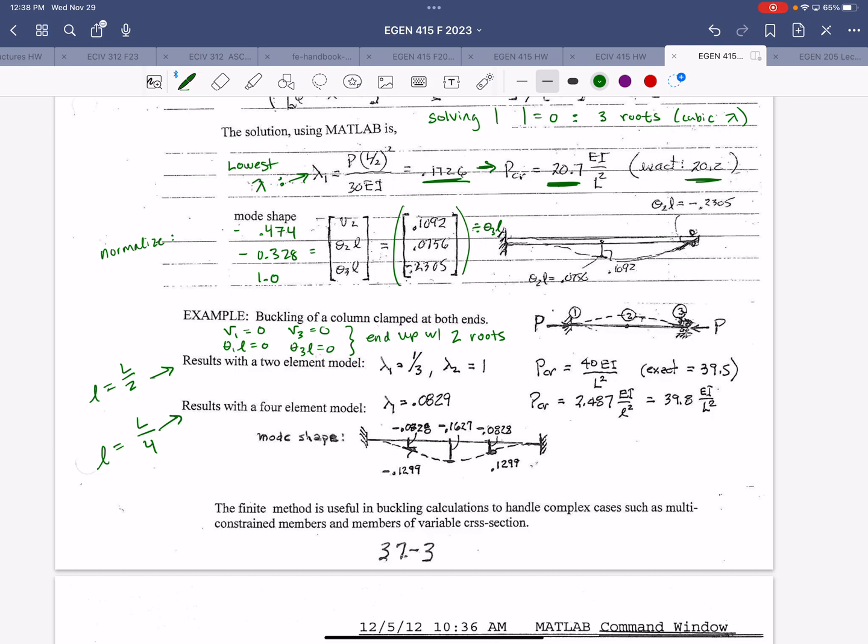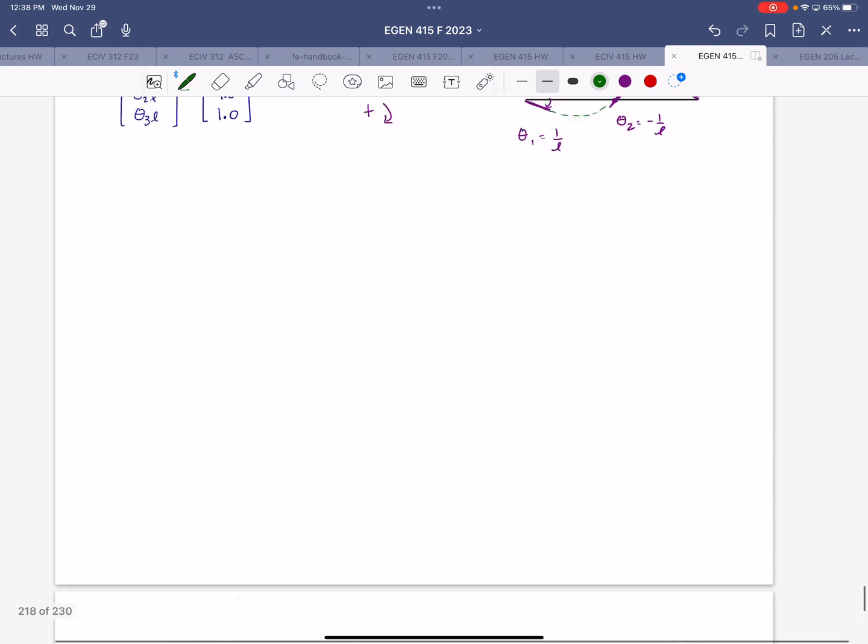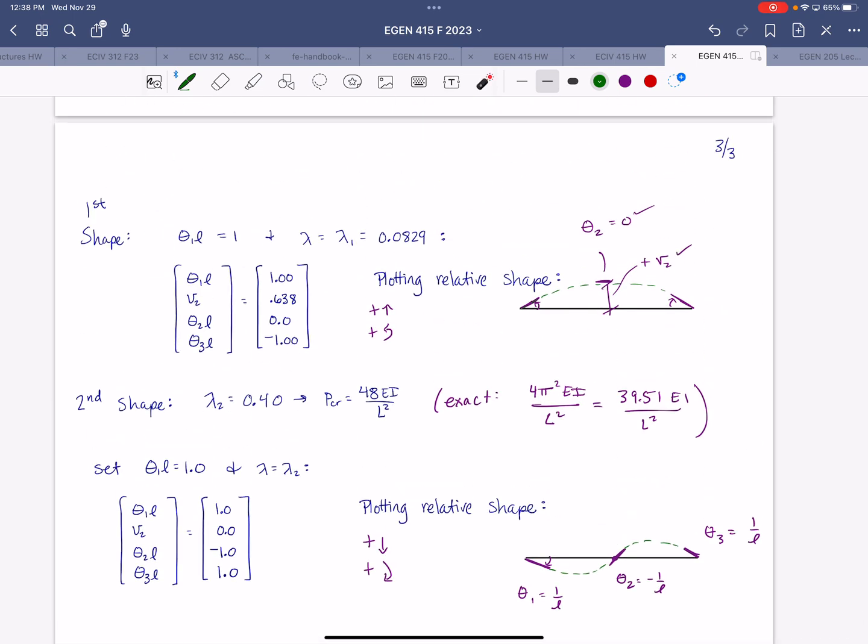But with that solution, it's more likely that the higher modes, right, because we looked at the second one in that case, so here's that inflection there. But we also saw that the result is not as accurate, right, for the higher modes. So if you want accuracy in the higher modes, you might need to refine your solution more than you would for the first mode. Right. Well, and if it had another mode of buckling, like if it buckled another time, but we only have 3 nodes in this thing, it'd be kind of difficult to plot what the shape is a little bit, right?